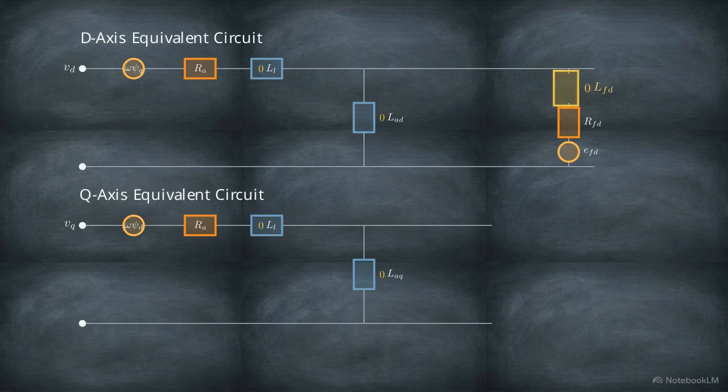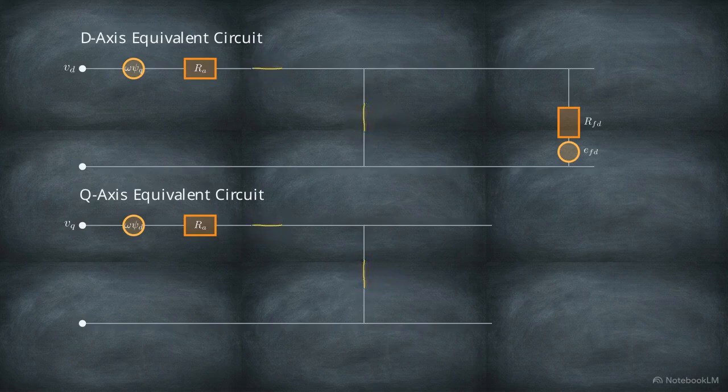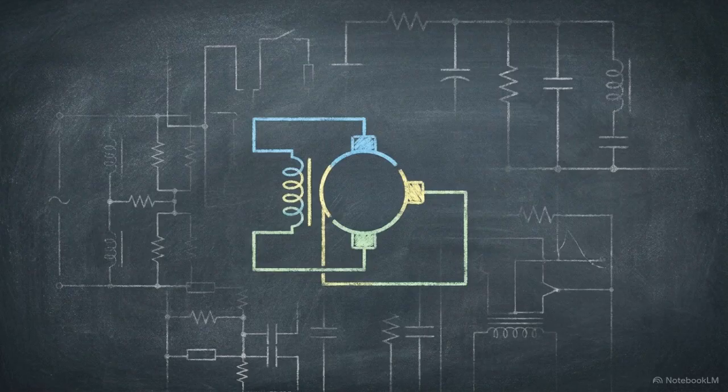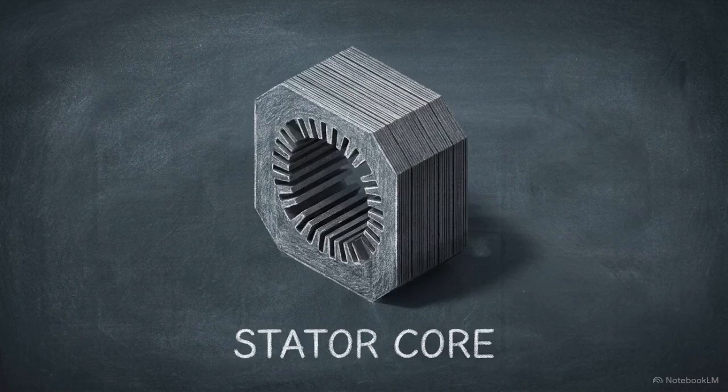Next is the field winding. During a transient, this branch carries dynamic flux, but at constant speed, the flux is static relative to the rotor. Its derivative also drops to 0, and the entire branch becomes a simple short-circuit equivalence. Steady-state equilibrium effectively neutralizes the generator's internal transient pathways, leaving only the core stator parameters to manage.